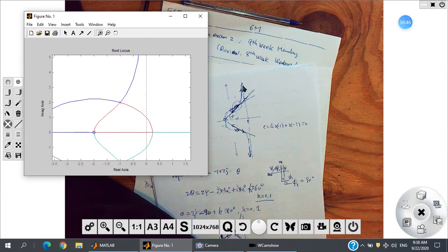Have both. Yeah, this one here. This is a curve for the positive K, right? Positive K. So it's this one, positive K, and the departure is up and down. And the left and right, they are the arrival direction, arrival to this pole for the negative case. And for this circle, this 0, up and down, they arrive, right, for positive K. And then along the real axis, they are departure for the negative case, from negative infinity, coming up to 0, and then positive, right? Things like that. Okay, this is multiple 2.